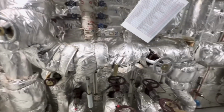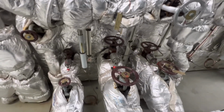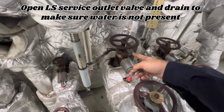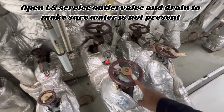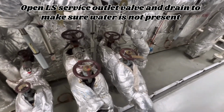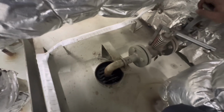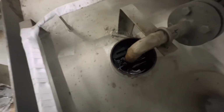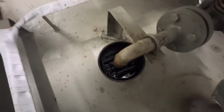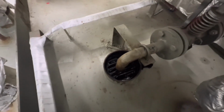So now this is the low sulfur service tank. This is the outlet from here. These are the two valves. This is the quick closing valve, which is always open, and this is the manual valve, which we will open now. Before opening this one, we will drain a little bit of oil from here, or water. We will check the condition of the drain. We will make sure no water is there. You can see the clean oil is coming, so no problem.